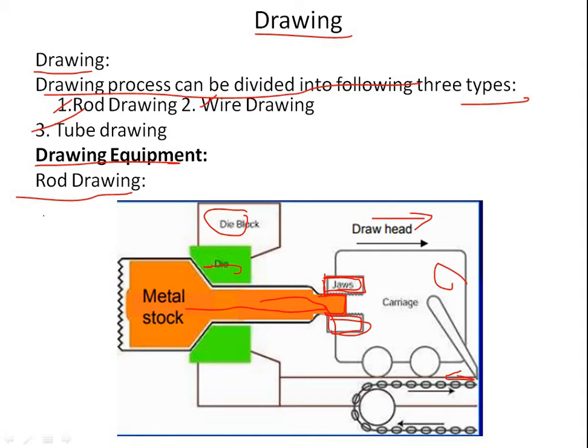Okay, we are discussing rod drawing here. In that, first will be cleaning before drawing. For steel rods that are previously hot rolled or extruded, surface cleaning is required here. For this, the material is immersed in a dilute hot solution, around 75 degrees Celsius, of hydrochloric or sulfuric acid. This is termed as acid pickling.